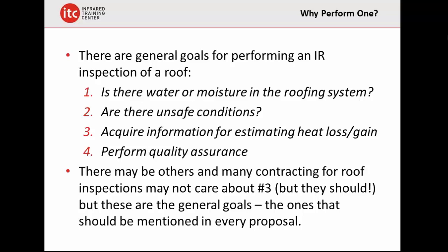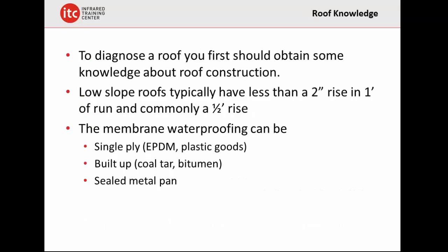The other application for IR here would be to perform a quality assurance test. A manufacturer might want to use an IR camera to make sure that the installer performed properly. If it was a roll roof, they want to make sure that they get the proper end lap and side lap, like on rolled roofing. So that'd be another one. A lot of reasons why you might want to perform a test. Now, in order to diagnose a roof, you should first obtain a little bit of knowledge about roof construction.